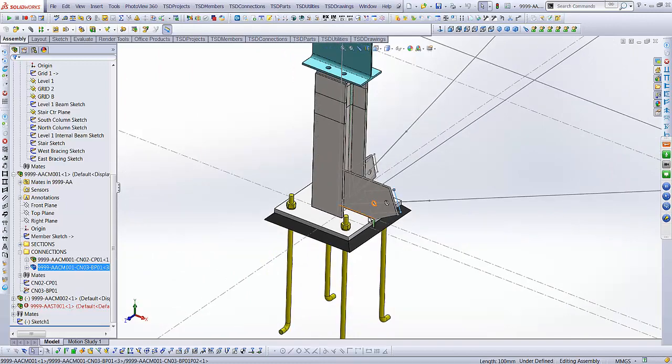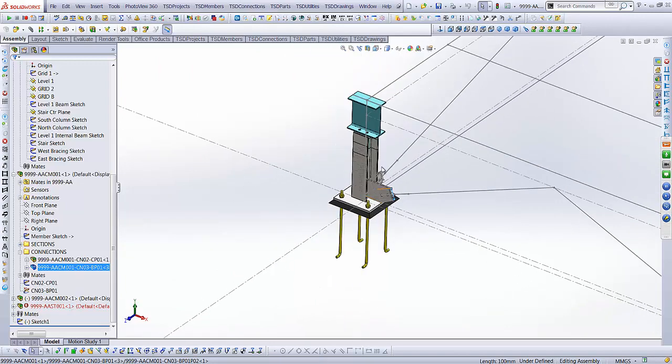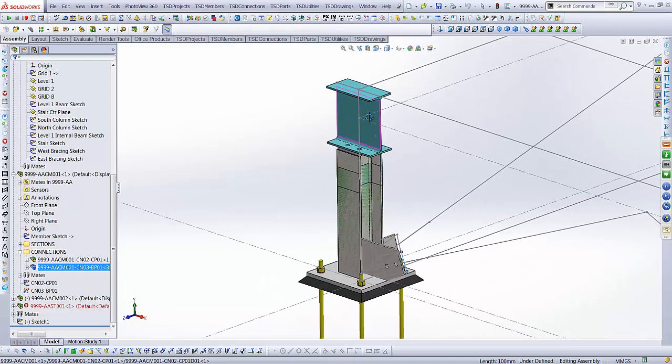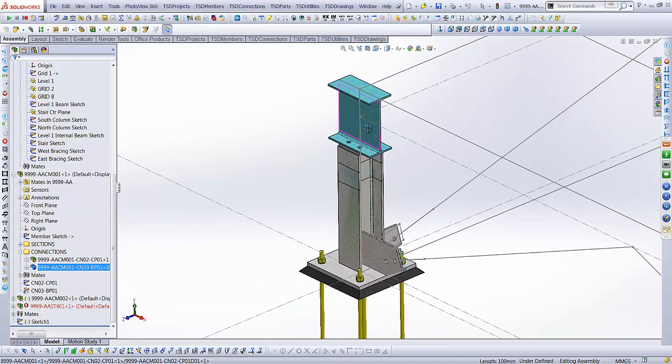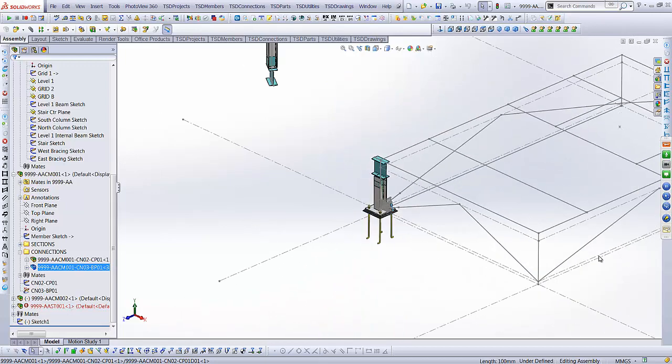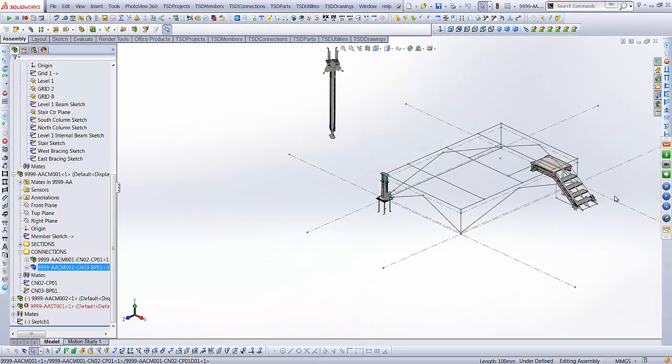So now you can see how sketches influence the process, and you can see that column is updated because of the 1 meter height that I gave it. So for small platforms and things like that, you can actually reduce this. It's quite an interesting process, but you can. And the stairs themselves, looks like that piece has fallen over there. Maybe it might need a rebuild.